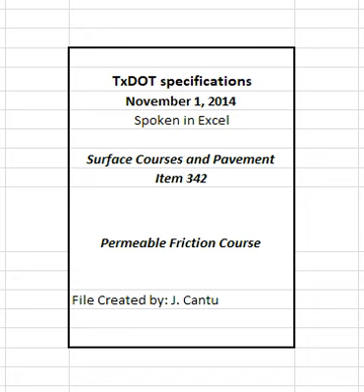The aging ratio is the DSR value of the extracted binder divided by the DSR value of the original unaged binder. Obtain DSR values in accordance with TxDOT T315 at the specified high temperature performance grade of the asphalt. The engineer may require removal and replacement of the defective material at the contractor's expense. The asphalt binder will be recovered for testing from production samples or cores in accordance with Tex-211-F.